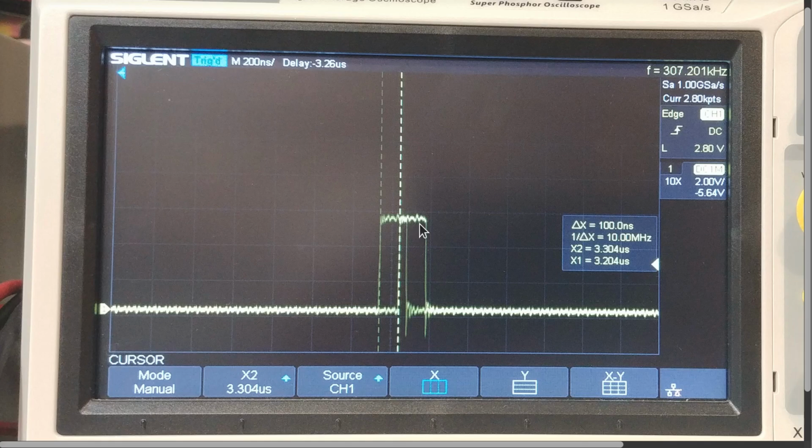If you look at a 100 nanosecond error that is fixed, because remember, that's the period of phi, which doesn't have anything to do with the CTC's bit rate clock input and the divider and all that other fun stuff, the jitter will always be 100 nano if you have an input that you're using to tick your timer that is not phase locked to phi. It will jitter at 100 nano, okay?